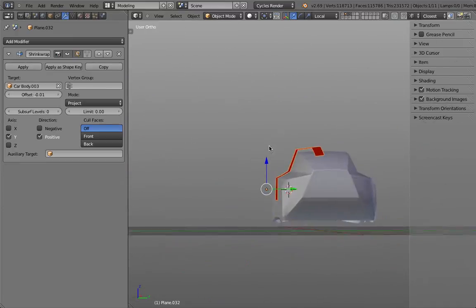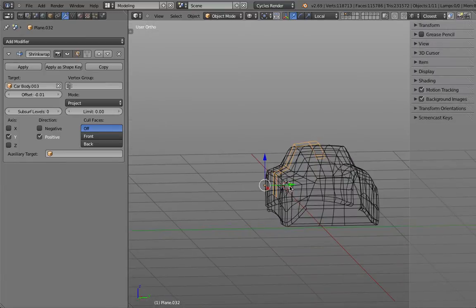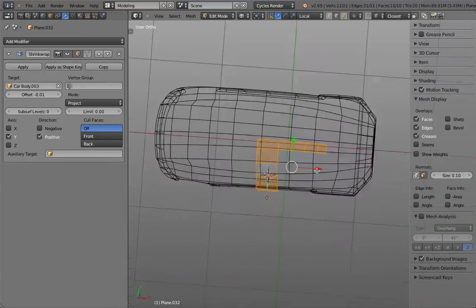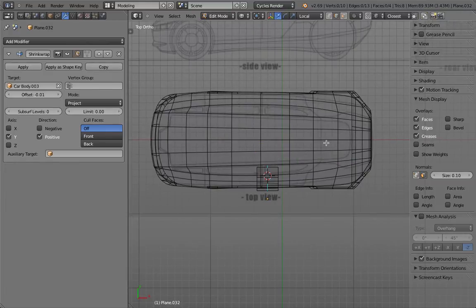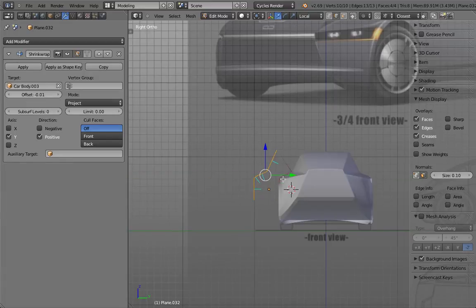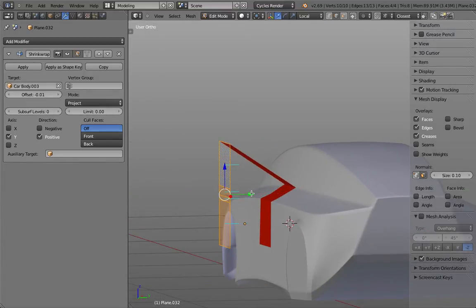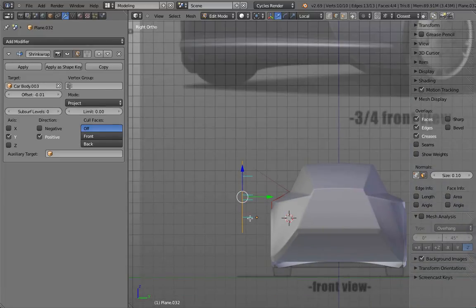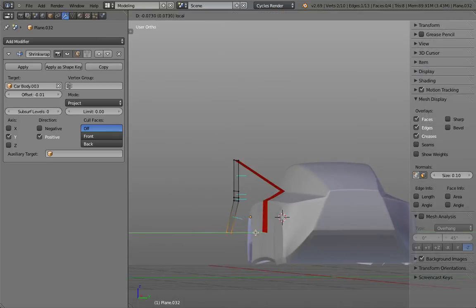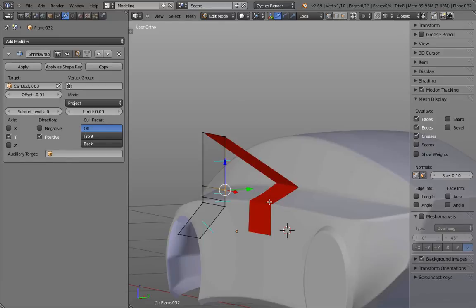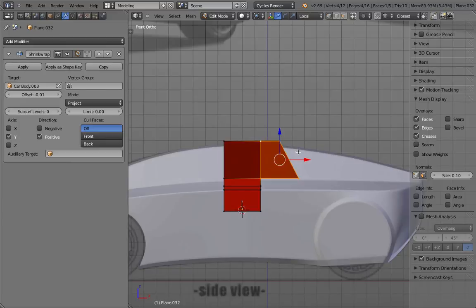Now, when you use Y, for example, it works a little bit different. Y is actually a very simplified approach. So, for example, all Y allows me is kind of like project something straight along the Y-axis. So, for example, how a face is oriented doesn't really matter because those points are being straight projected along the Y-axis. So, for example, if I extrude this one out and extrude this one out, there you see like how perfectly it fits on it.